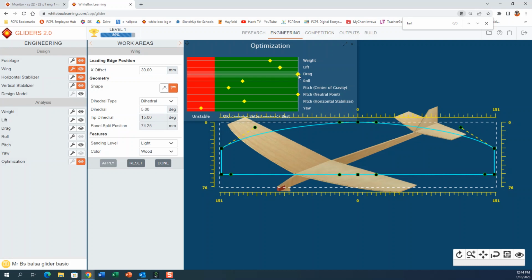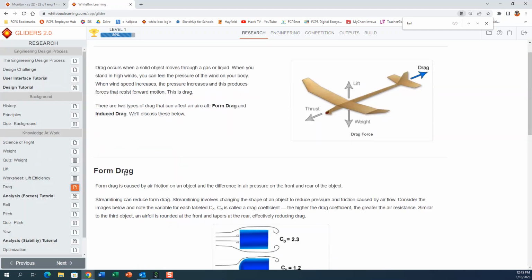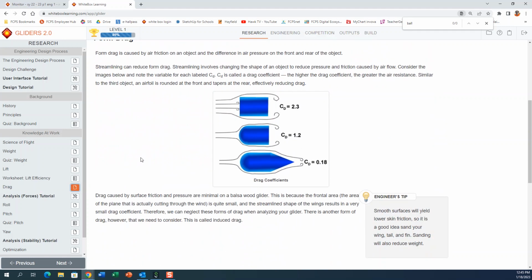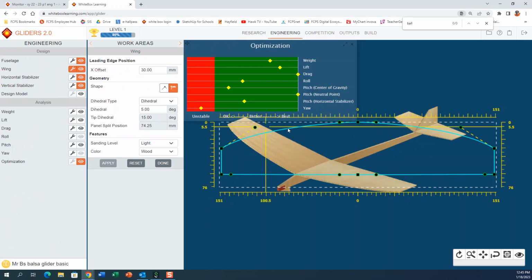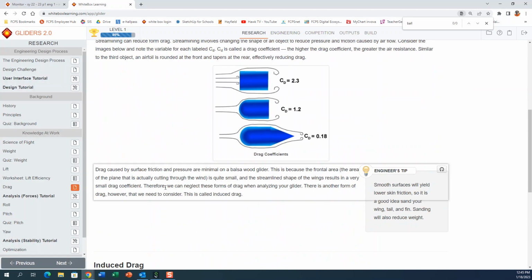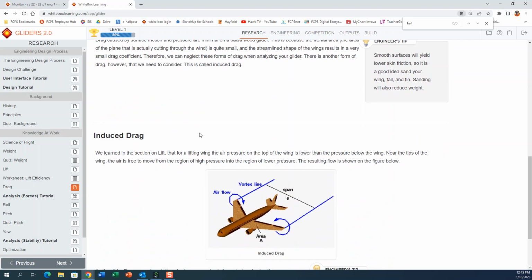So next one is drag. Well, our drag is excellent, okay? But let's go ahead and do a quick review of that as well, okay? Just switching to that round geometry, getting away from this nothing but straight lines of our wing, these curved lines here, dramatically improved our drag because smooth surfaces allow air to flow more naturally and faster, creating less drag. So just by going with the curved edges, that really helped a lot.